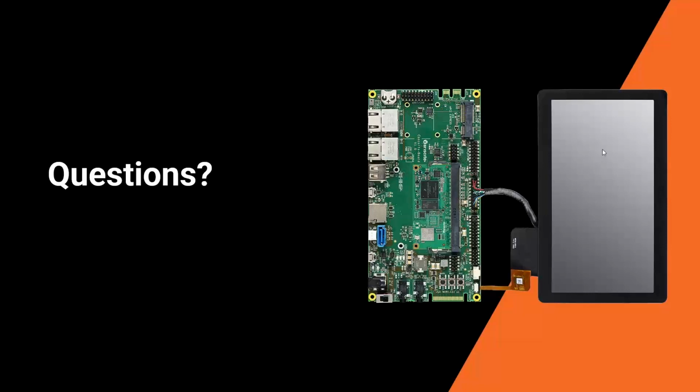So if you like, we can go through the questions, if any. We have a question about whether LVGL uses CPU or GPU for 3D rendering. LVGL allows using 3D through specific APIs, but the 3D support comes from the microcontroller world for LVGL. For the Linux world, there is a kind of 3D support only when using SDL.